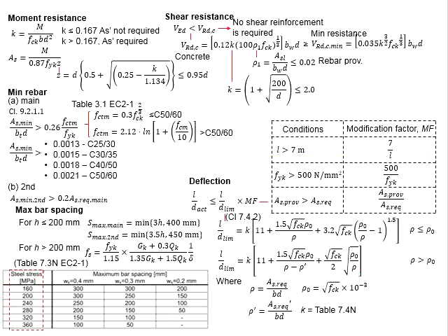We mentioned that normally staircases do not require compression reinforcement bar. That means there is a chance that the L per D ratio is going to use the first equation here. However, there is no guarantee that it always falls here.